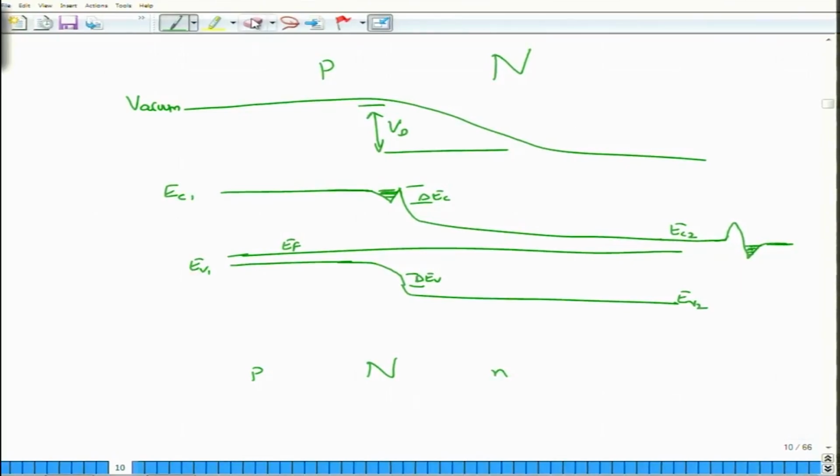Eventually, the region here on the N type material would actually have the same value of EC. So, we will call this EC3. This one would simply drop, have a sudden transition and then move back to EV3. Okay. The Fermi level, of course, I did not write it correctly, but the Fermi level has to be constant. Okay. So, I should have written down the Fermi level first and then made these bends as such.